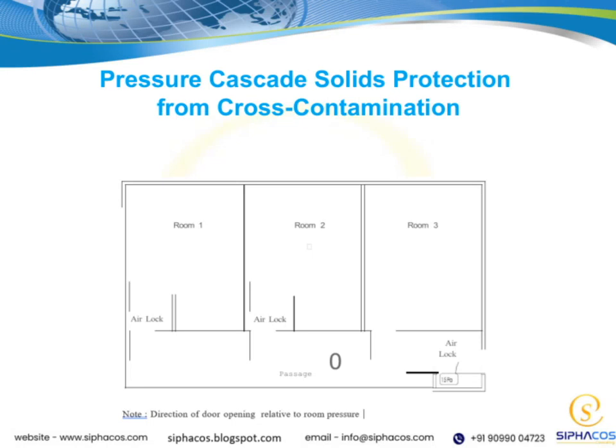Now, let's take a closer look at the pressure cascade solids protection from cross-contamination. This concept is crucial in maintaining the integrity of pharmaceutical processes. Essentially, it involves a carefully designed pressure cascade system that helps prevent solids from moving from one process area to another. By establishing a pressure differential, we can control the flow of materials and minimize the risk of cross-contamination.